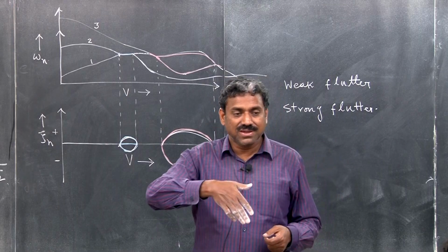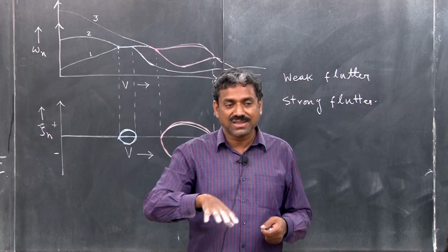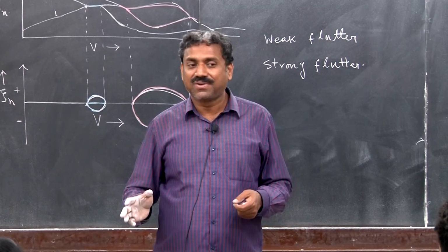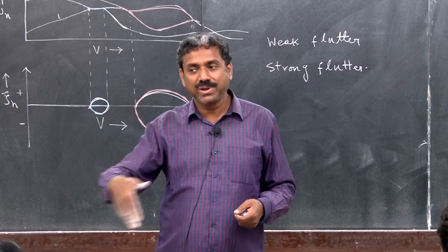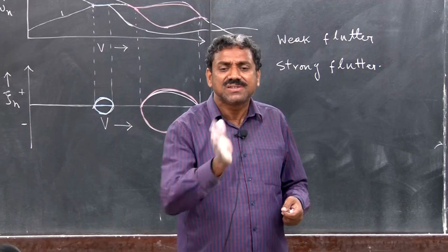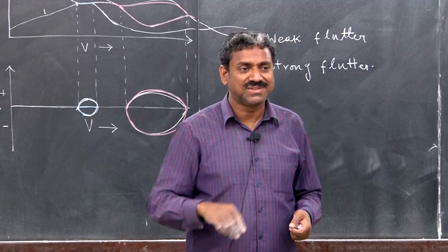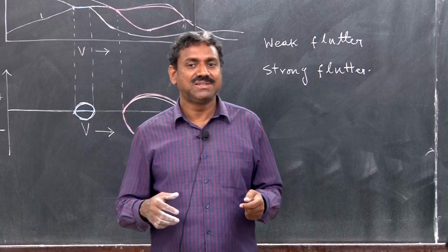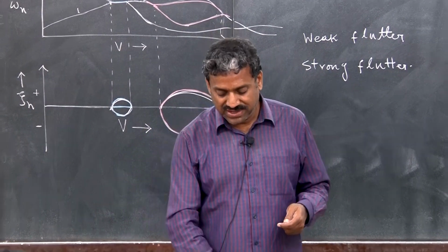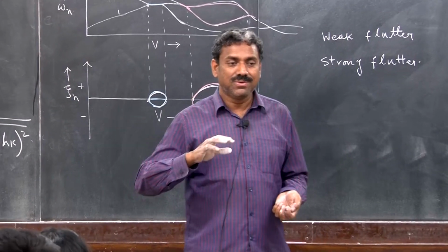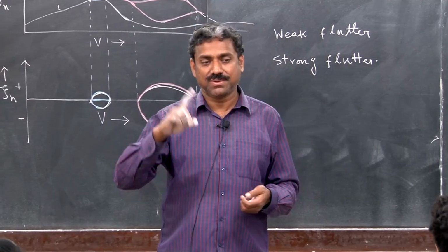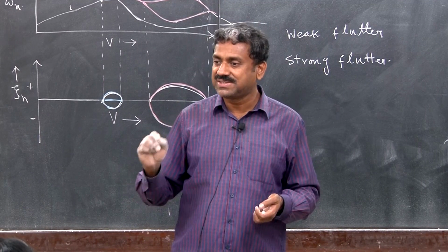So, the incoming airflow gets stuck, there is a stagnation point, and at the end downstream there is vortex shedding, and because of the vortex shedding it is not the along wind component, but the across wind component that is more important. There is a huge vigorous vibration across the wind, transverse vibration, those are across wind. So, in the code you will see that there is a huge discussion on across wind and along wind, and on how much shear force is going to come. When you design, after that you have to do a little check of how much shear force is coming from the wind tunnel test and how much is coming from your design value, okay.